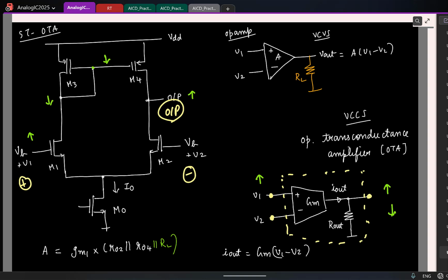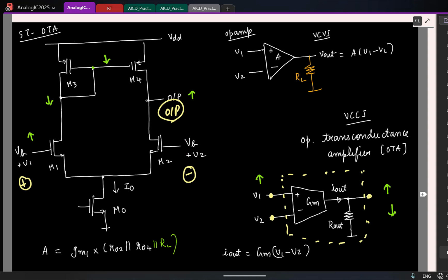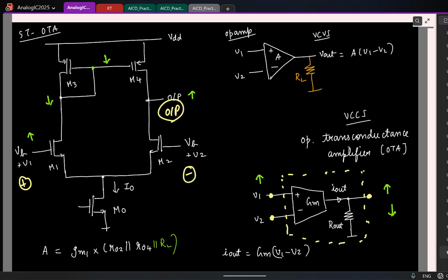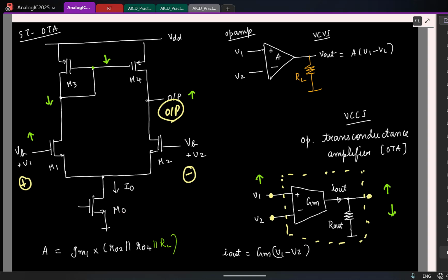So anyways, if you recollect, we computed the small signal gain of this circuit by finding the short circuit GM and RO. That's because we noted that the circuit was asymmetric, so doing common mode and differential mode calculations might not simplify my circuit. That was the logic. But we also made another observation: although this is asymmetric, are there some conditions in which it becomes symmetric?